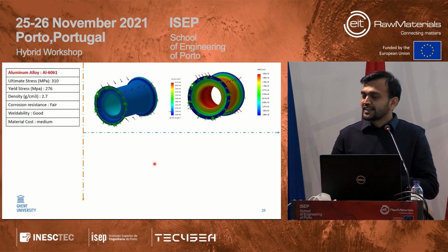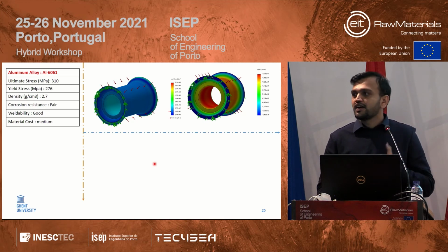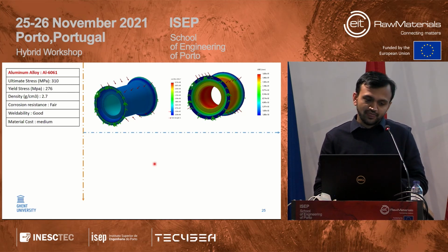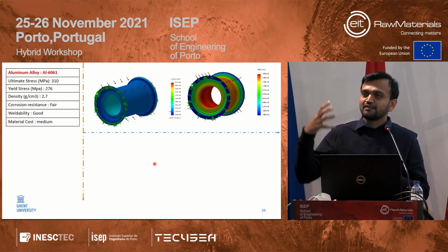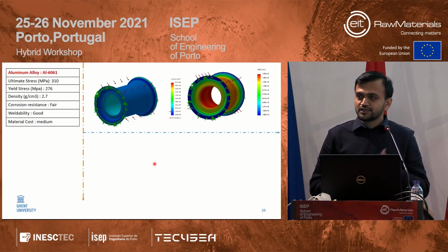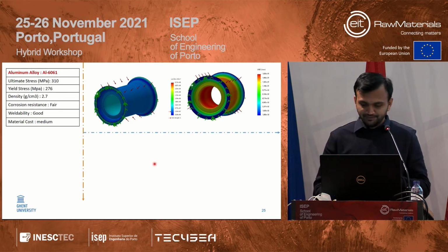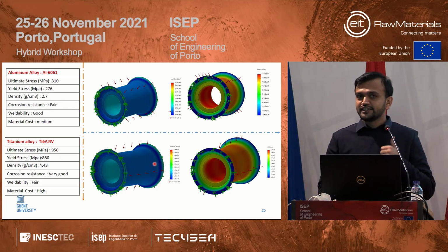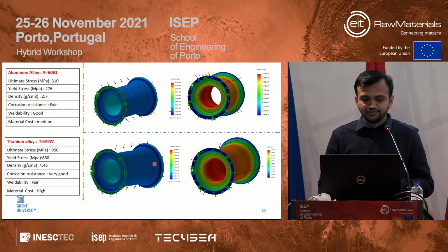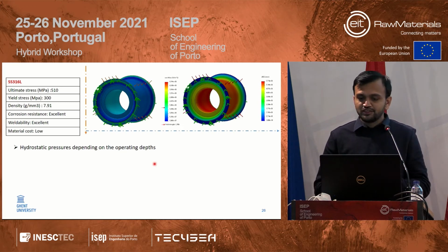As my colleague explained, she considered 3 different materials: aluminum, titanium and SS316 stainless steel. Now consider a housing, and we apply a hydrostatic pressure, a compressive load, on the housing, and we see the strength and the mechanical characteristics like the deflection and the buckling. We did 3 different simulations on FEM for the 3 materials. We introduced hydrostatic pressure on a housing, and we checked its stress, deflection and deformation.